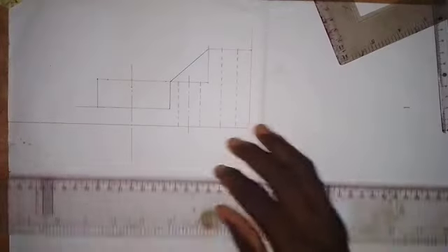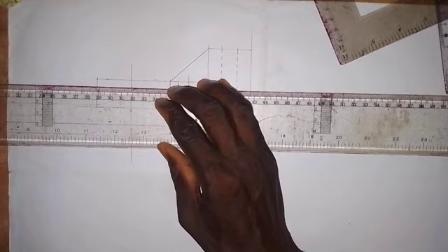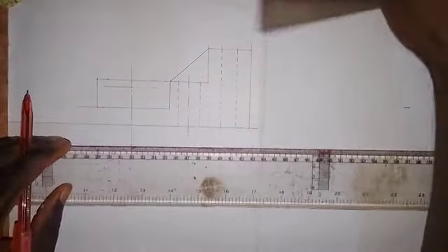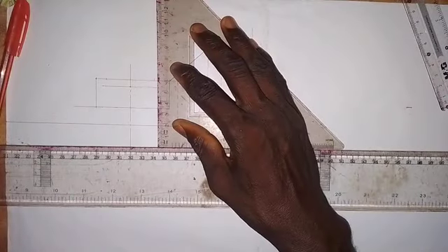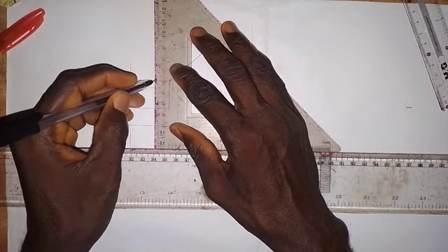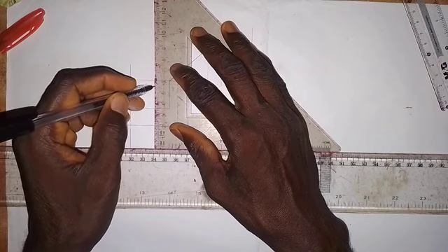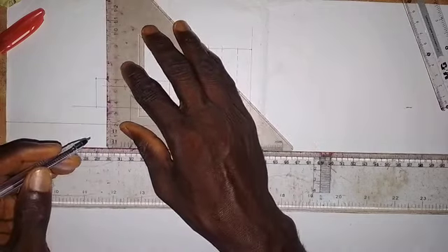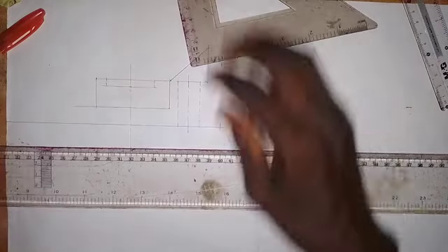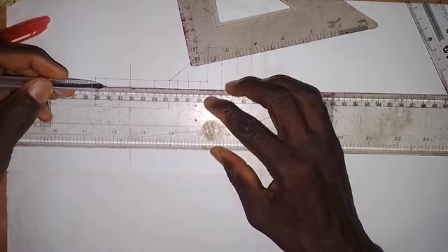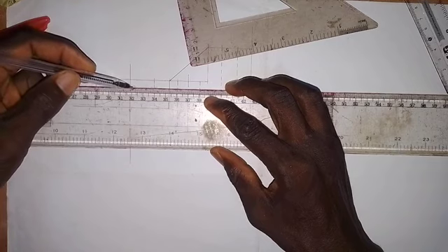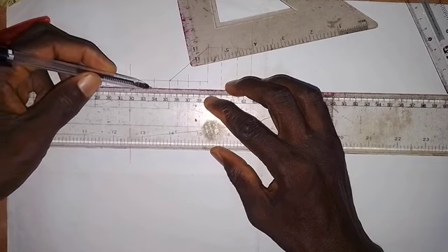At this point I'm going to draw a horizontal line from here to this side. Then I'm going to draw a vertical line. It will be drawn with a short dashes line because that is hidden from us. So we just draw a short dashes line, just put 2 dashes there. And then we also do the same thing here. This also should be drawn with a short dashes line. All right, so we have this now.